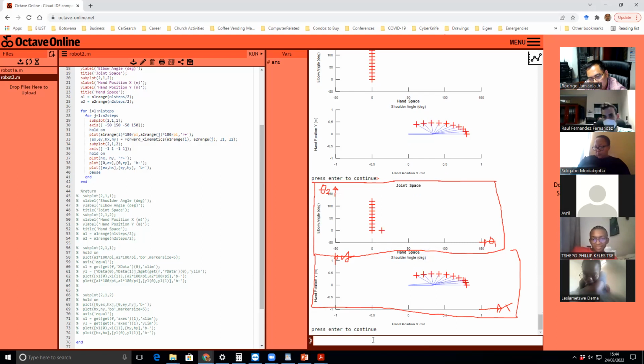Now let's move theta 1 a little bit. Because theta 1 now is not 0, it rises up. Again, we increment joint 2. So we're just plotting the values of the joints, increasing the values of the joints, and we're also looking at what happens to the hand. Of course, it will just sweep like that, because we change the values of the joints. Please pay attention because you will do this program on your own.